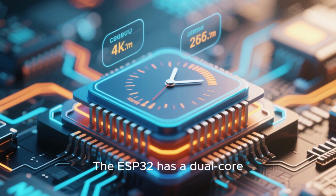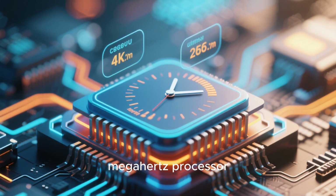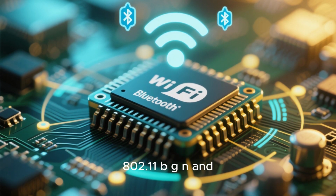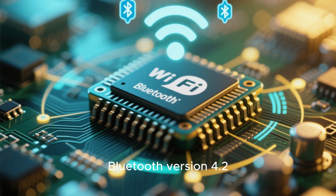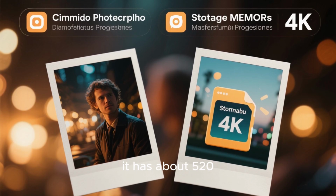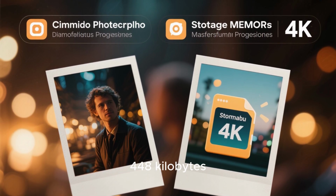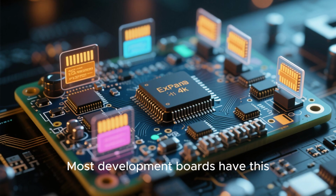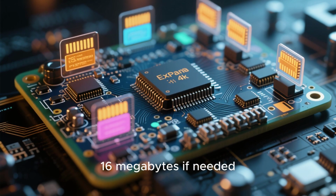The ESP32 has a dual-core Tensilica 32-bit microprocessor running at up to 240 MHz. It comes with built-in Wi-Fi 802.11 b/g/n and Bluetooth version 4.2, which is both Classic and BLE. On the memory side, it has about 520 kilobytes of SRAM, 448 kilobytes of ROM, and 4 megabytes of flash. Most development boards have this amount of flash, but it can be expanded up to 16 megabytes if needed.